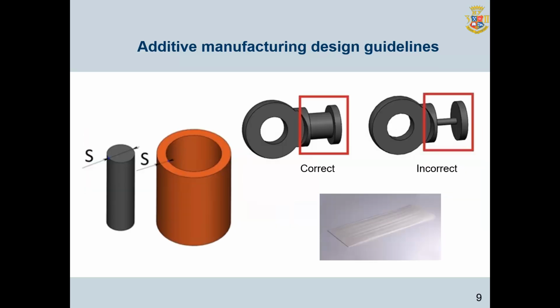One of the main requirements for the design is the need to comply with the minimum wall thickness of the model and its elements. First of all, the minimum thickness depends on the material used and the printing method. The use of models with minimum wall thickness is allowed, but not recommended. The walls must be equal to or thicker than the nozzle diameter. That is, the wall thickness should be a multiple of the nozzle diameter.